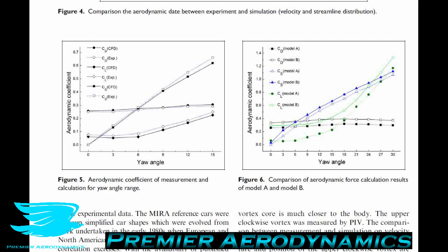So let's recap a few things that are important for this podcast. The first thing is that the car is traveling at 108 kilometers per hour. So this is quite fast, and this is now in the part of the velocity where the car's drag and aerodynamics in general are very important. Below about 60 to 70 kilometers per hour, a car's drag is typically seen as less important than the friction, like the rolling resistance of the car on the road.